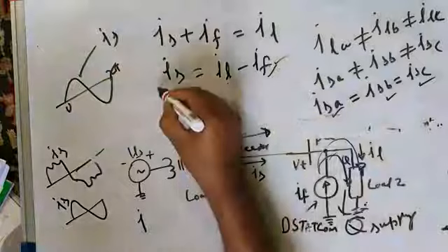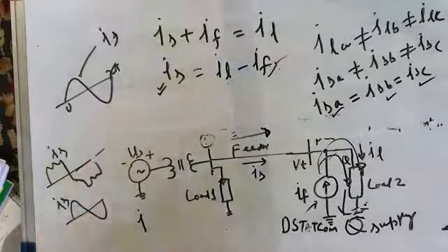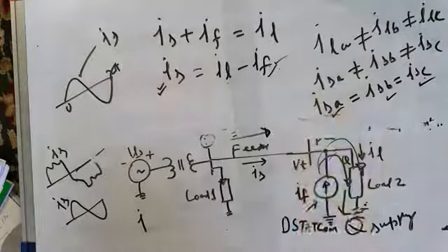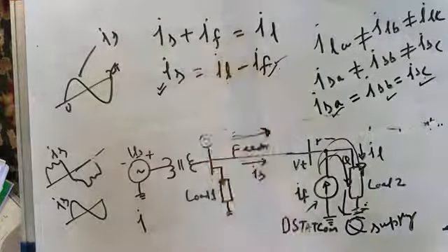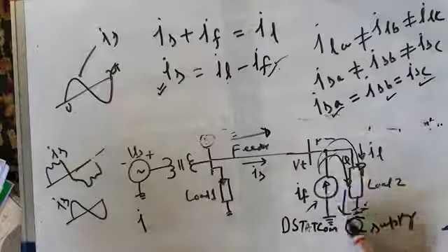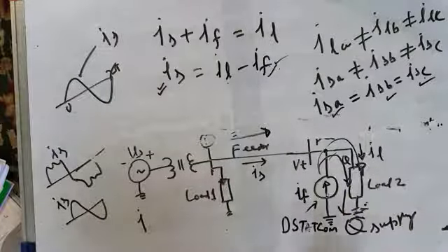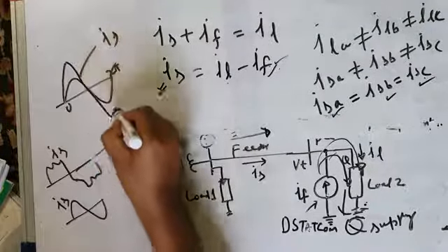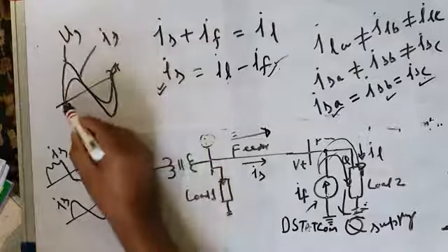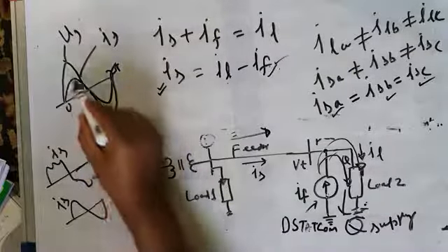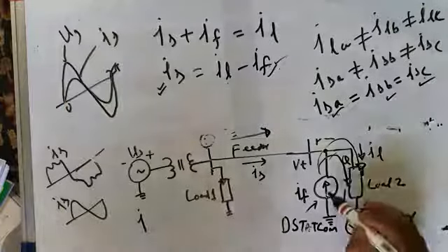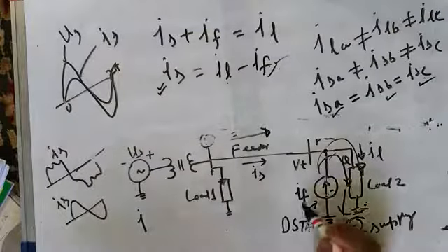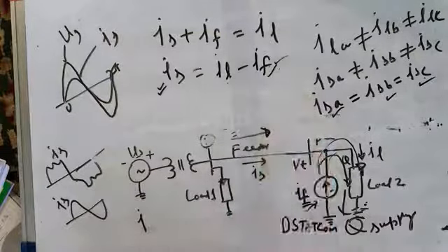उसकी वजह से जो आपकी source current बन जाएगी, वो एक तो balance बन जाएगी with ISA equal to ISB equal to ISC, जिससे आपकी bus voltages भी balance रहेगी. और ये सोर्स करंट फ्री ऑफ हार्मोनिक्स हो जाएगी बिकॉज ऑल हार्मोनिक्स आर कंपनसेटेड बाय दिस फिल्टर करंट इटसेल्फ. और ये सोर्स करंट इट विल बी इन फेज विद द सोर्स वोल्टेज. अगर आप वोल्टेज देखोगे, दिस इज सोर्स वोल्टेज, यू विल सी ये source current will be in phase with the voltage. Why? Because all the reactive power demanded by the load is supplied by this D statcom filter current. No reactive power is now coming from the source.